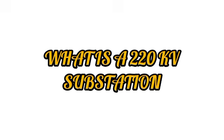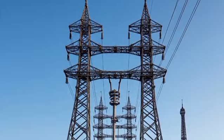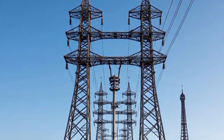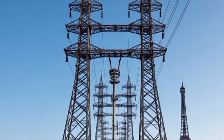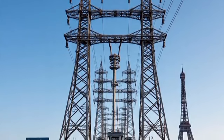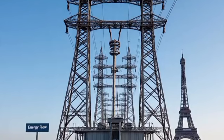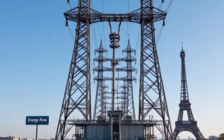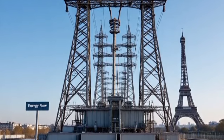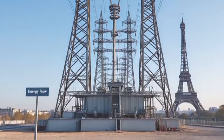What is a 220 kV substation? A 220 kV substation operates at a nominal voltage of 220,000 volts and is typically part of the high-voltage transmission grid. Its core function is to either step down voltage from higher levels, for example 400 kV, or step up voltage from lower levels, for example 132 kV or 110 kV, depending on the power flow direction.